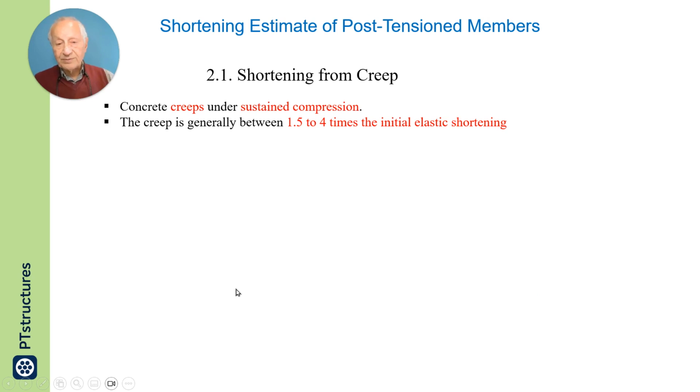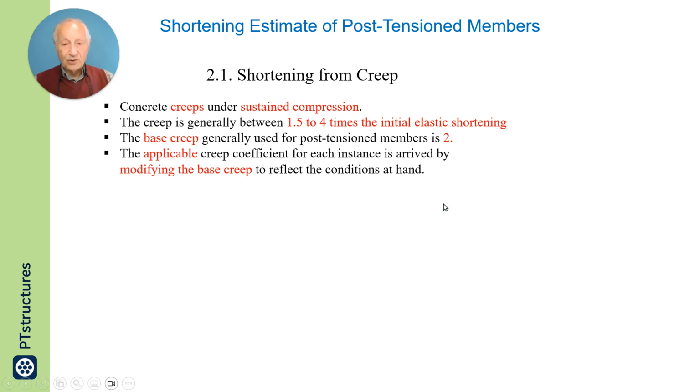Now we come to creep. Creep is taking place under sustained compression. The magnitude of creep is generally between 1.5 to 4 times the initial elastic shortening. 2.5 is really the common value. The base creep generally used is assumed to be 2 times the elastic shortening.